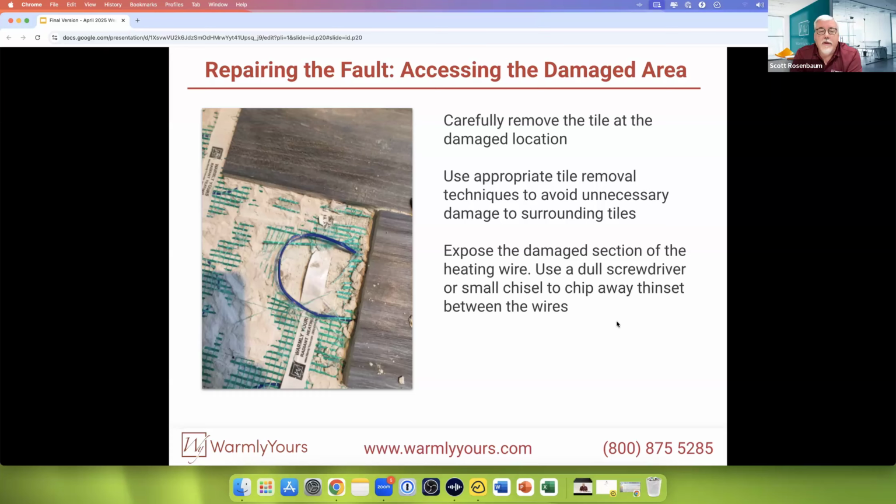The one thing that's great about this picture is that probably one of the biggest bits of misinformation out there, supplied by electricians troubleshooting these situations, is that there's a problem in the floor and you're going to have to replace the entire floor. You don't have to replace the entire floor. You find the spot where it is and take up that tile. When you do the tile, don't try to lever it up off of another tile. Just take the tile and smash it, then start picking the pieces up and keep smashing it until you're able to lift it up.